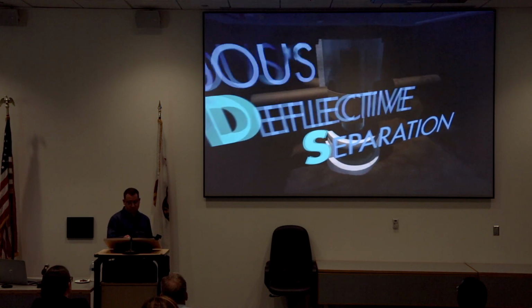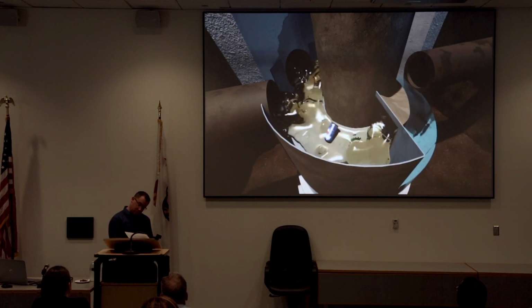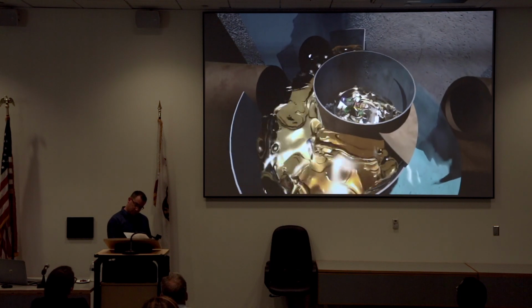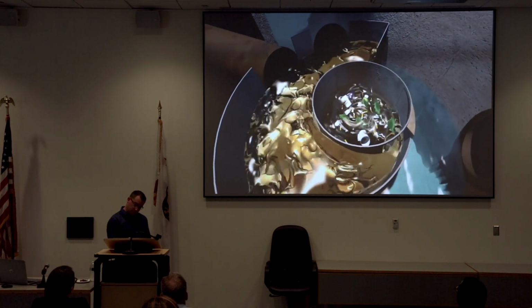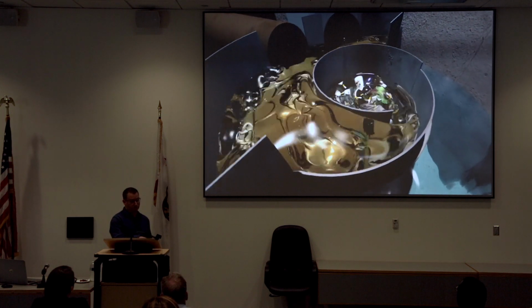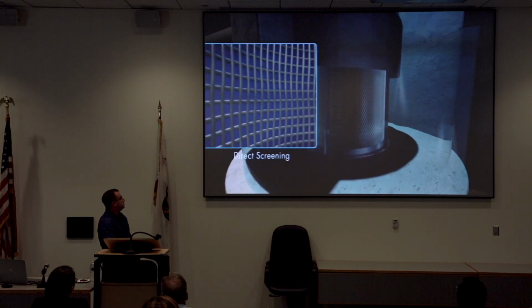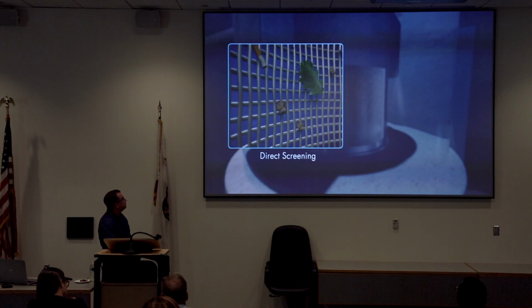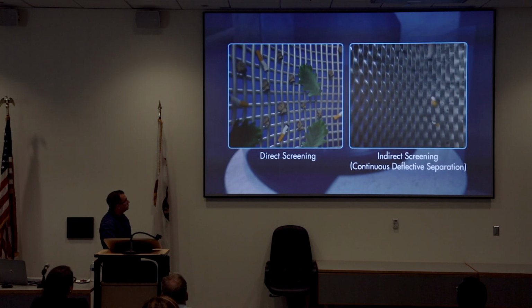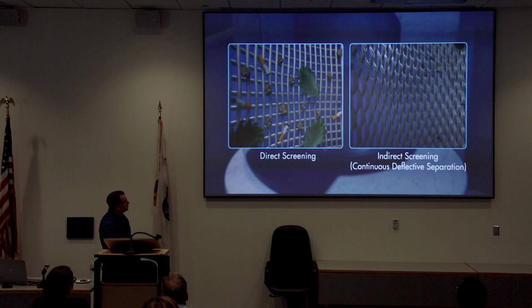The treatment process begins as stormwater enters the system through one or multiple inlets. The inlet flume guides the treatment flow into the unit's separation chamber, where water velocities within the chamber create a swirling vortex. At the heart of the CDS system is a unique indirect treatment screen. Unlike traditional screens that can easily become clogged, water velocities within the swirl chamber continually deflect debris off the specially designed screen to keep it clean.